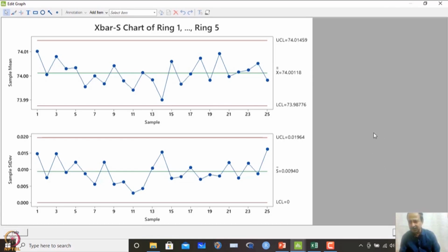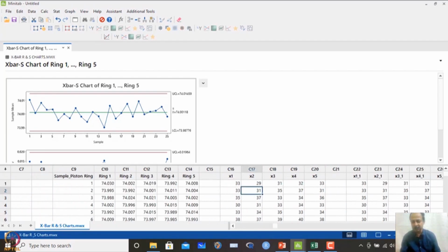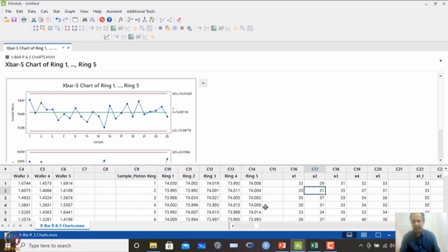Okay. But scenarios may not be so favorable. When you collect the data for the first time, what can happen is that some of the points can go outside the limit line, when we have not implemented any rules like that. So, the operator also does not know. I will go to the process and say please collect the data, 25 observations or 20 observations, and then give me the data points. I will give you the control limit line after a certain time. So, let me analyze the data and I will give you some control limit lines. Then you monitor the process subsequently according to the control limit line.